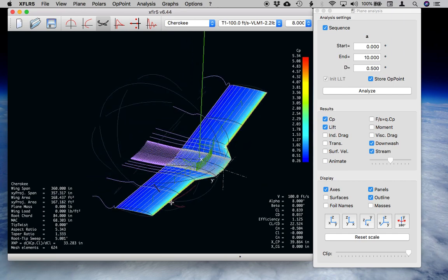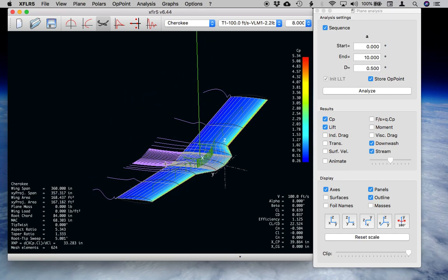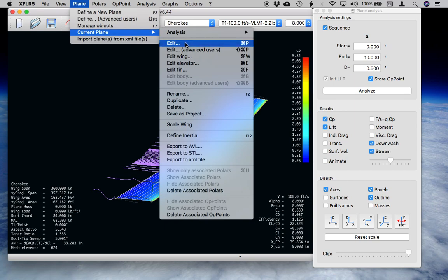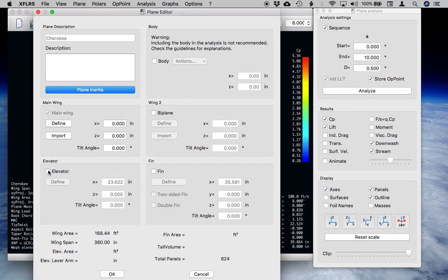Now once you've done this, then you can start to come in and play with a buildup on this. You can come back and look at your plane geometry. For example, you could add in that horizontal tail plane in the back. So you could throw this in here. This is actually going to be pretty close, so we're going to move this back a little bit farther.